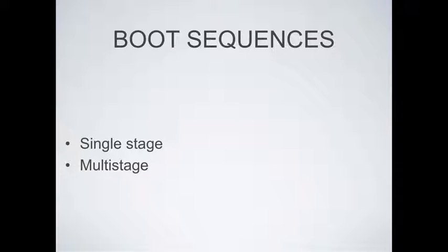So the type of boot sequences you might come across when a system is coming up from a power on or a reset, there are two types: either a single stage or a multi-stage. In a single stage, you more than likely are going to have some internal boot ROM. Processors and chips without internal boot ROM will possibly be doing the multi-stage boot sequence. When it has internal boot ROM, it'll just set up everything and start running. You don't have to copy anything from anywhere. So it's a single stage.